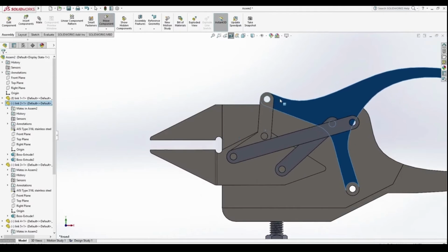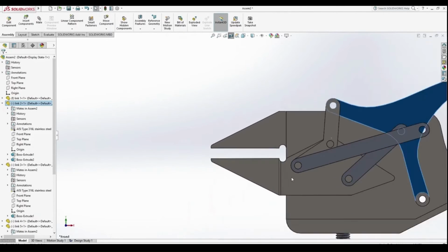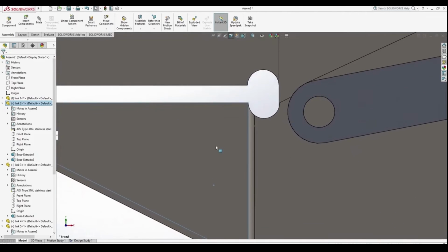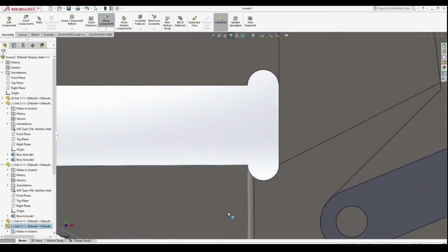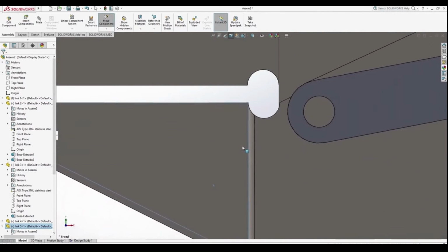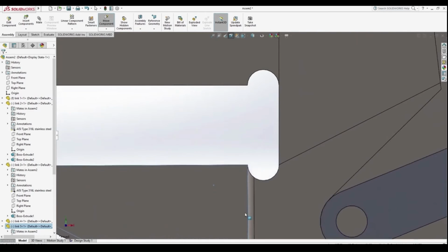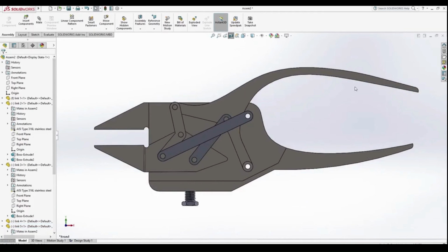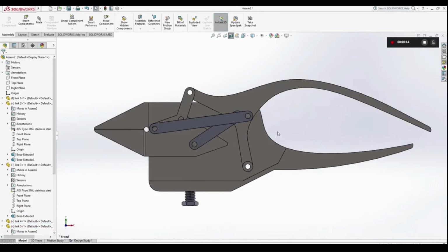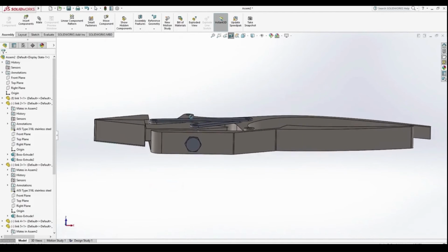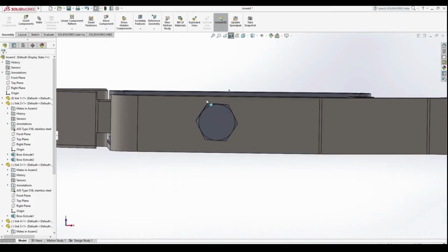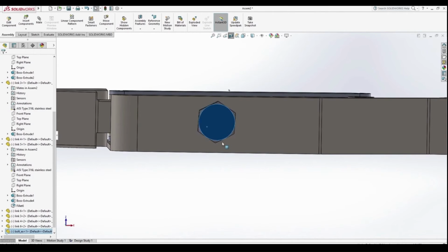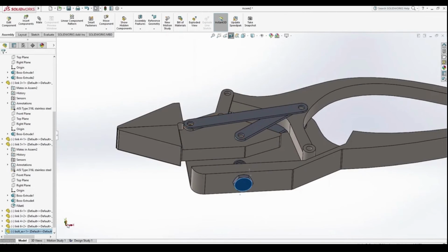These pliers are ideal for threading and flattening out kinks in wire, jump rings, fittings and much more besides, but they are also useful for creating nice, clean, blunt bends due to the uniform shape and sharp right angles. The screw in the lower jaw of the pliers helps in adjusting the maximum jaw opening of the pliers. It is of great use when the tool is used for substances having different diameters.